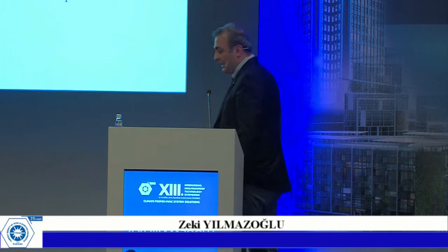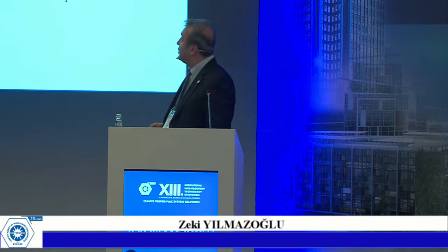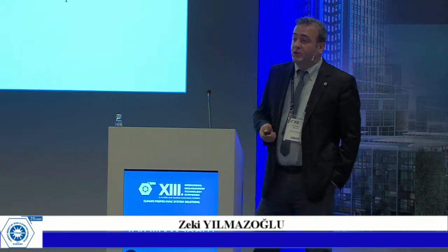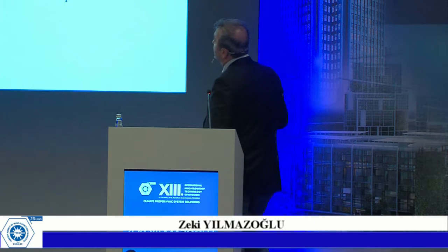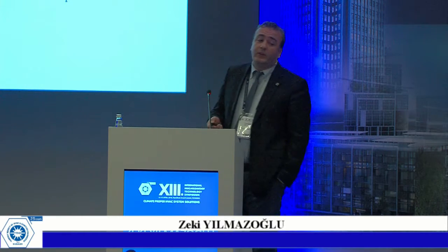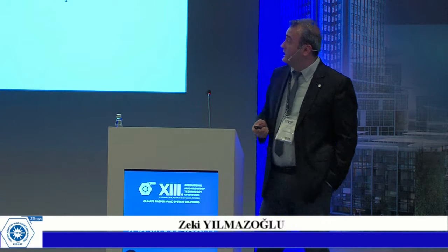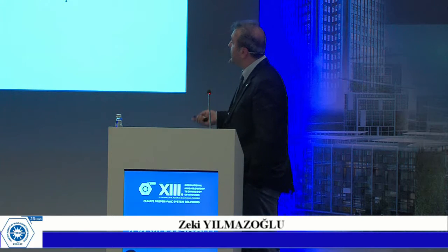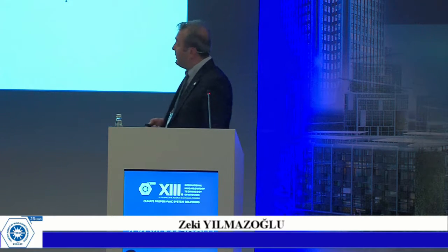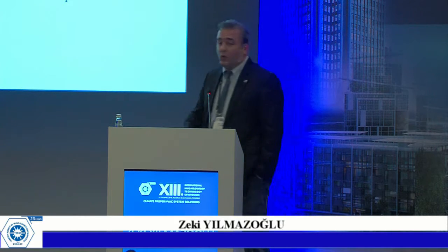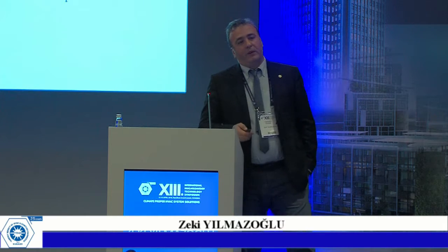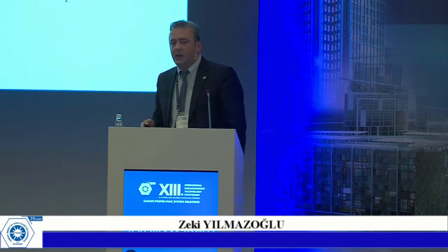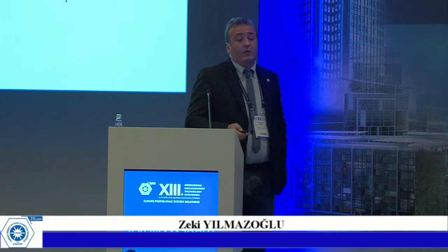There are many models used in modeling, such as Gaussian models, ASHRAE and customized solvers, Lagrangian and Eulerian models, which are CFD, computational fluid dynamics models, analytical calculation methods, and wind tunnel tests as an experimental study. CFD studies include comparison of turbulence models, the effect of mesh structure on the results, and modeling of the atmospheric boundary layer. If you want to model an urban area, you have to consider the atmospheric boundary layer and the effect of surface roughness.